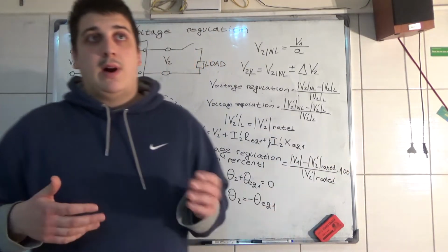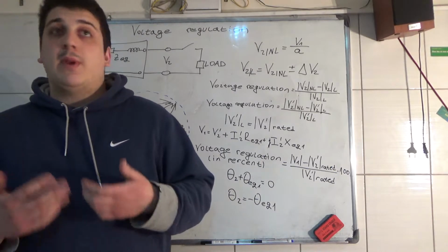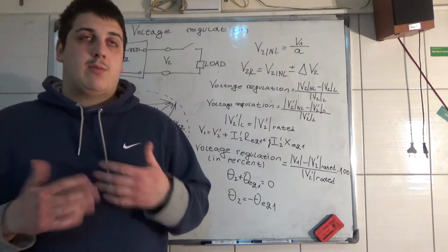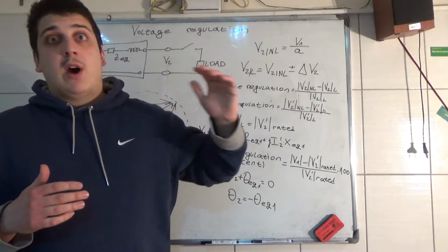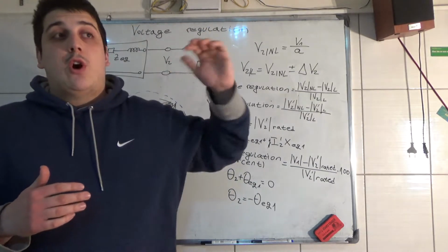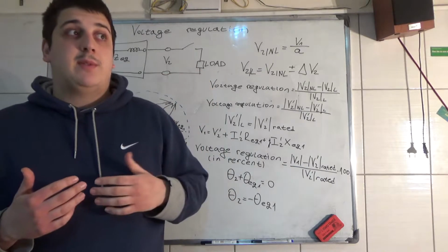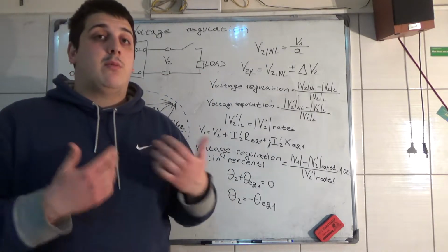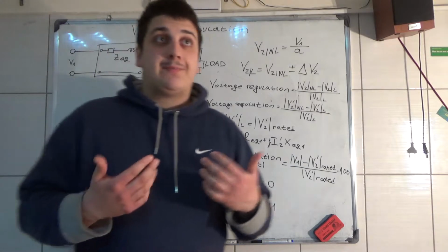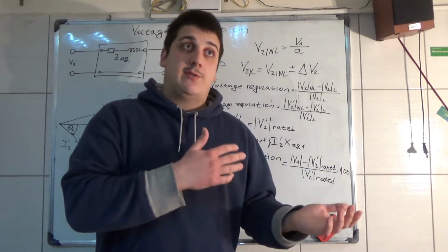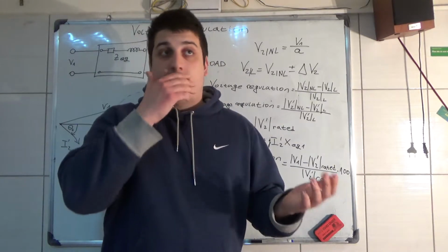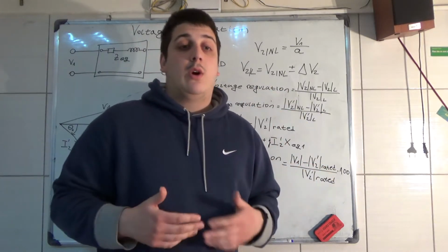That is also one factor, but the biggest problem is with the transformer, which doesn't have a constant voltage on the secondary, because sometimes more current is drawn, and then the internal voltage drop in the transformer affects the load terminal.